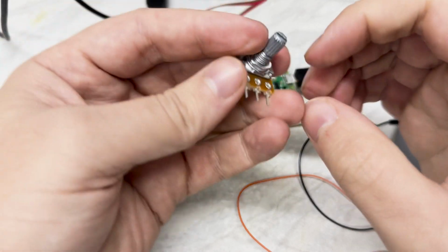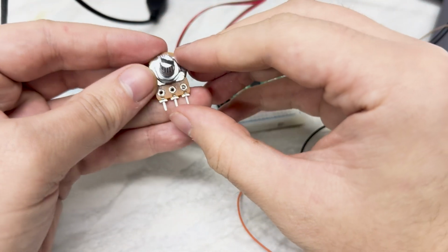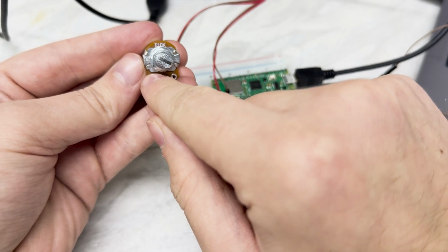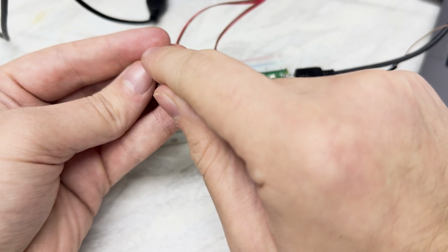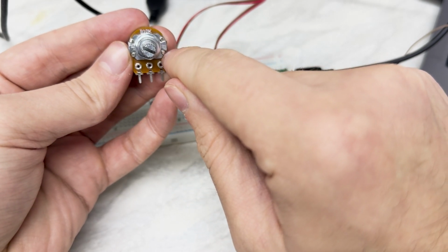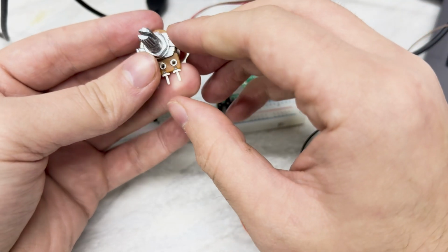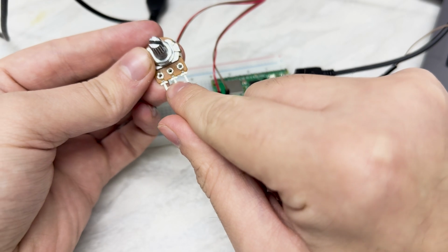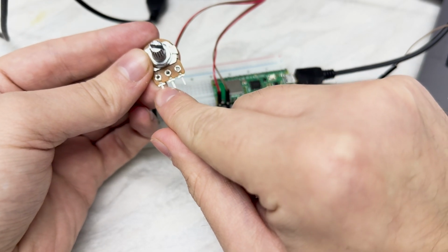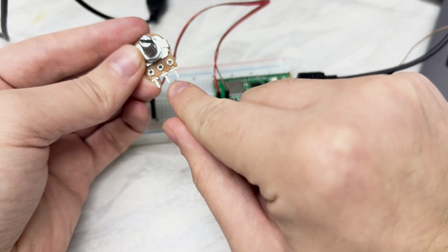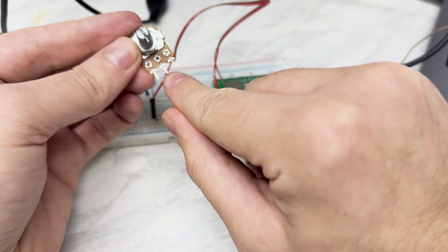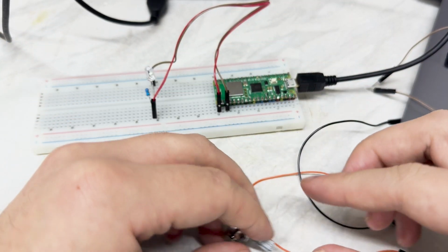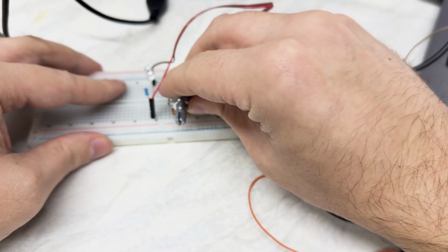And now here we have a potentiometer, so a little word on this. In this casing there is a resistive track that increases the more I go this way. Or at least it varies, maybe not increase. But what that means is that it's kind of a voltage divider, so if I put ground here and a voltage here, as I turn this, that will affect the output. It's like a voltage divider circuit. So let's start wiring this.